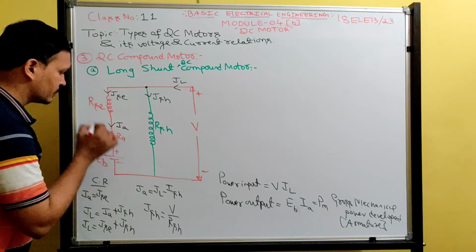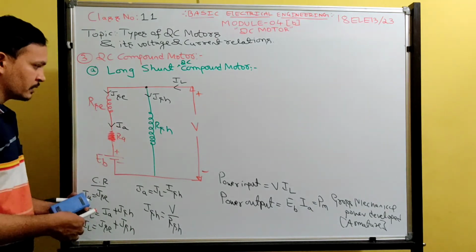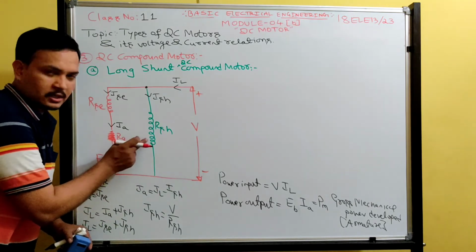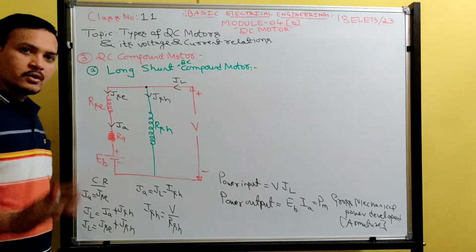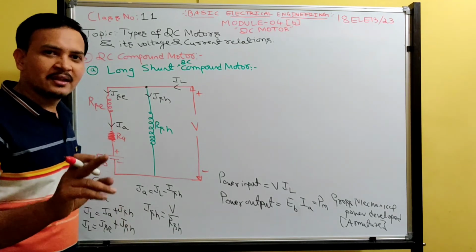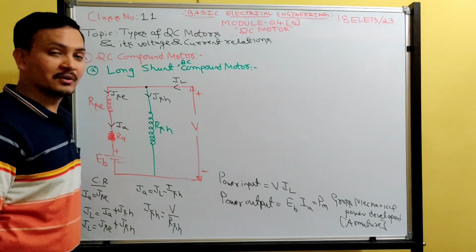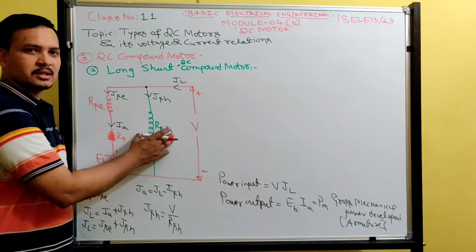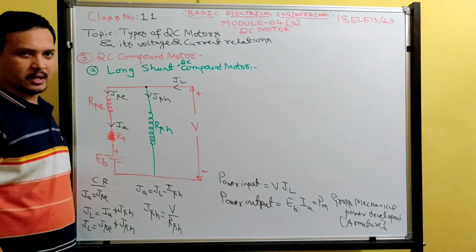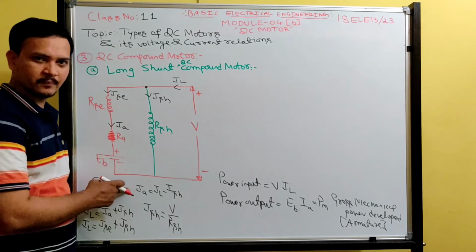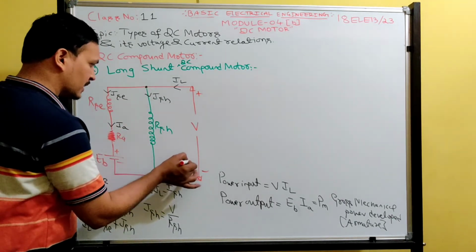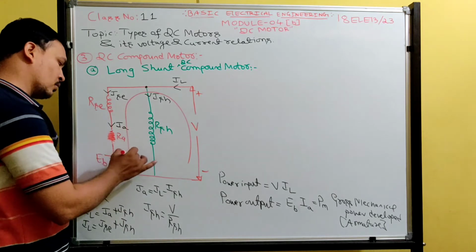So armature resistance. Now the shunt field winding is there. Whenever a shunt field winding is there, don't consider it for applying KVL. While writing the voltage relation, you throw it to one side, because the effect of ISH is already in the current relation. Therefore you should apply KVL to the outer loop.